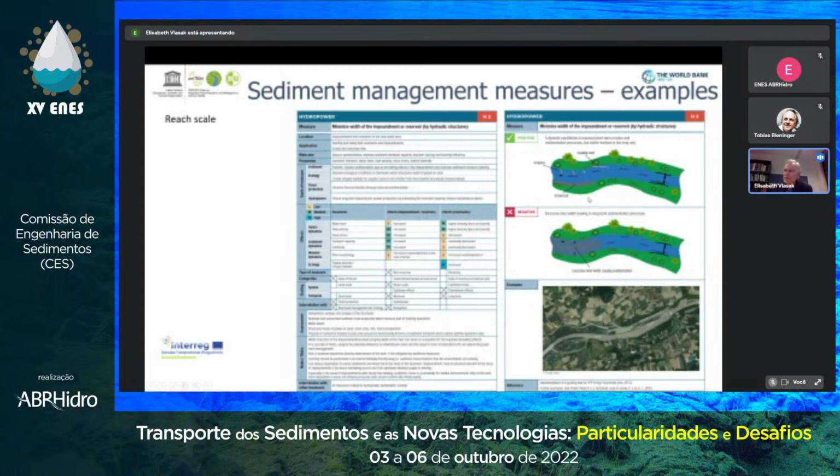Unfortunately, in our conditions in Austria, we have many reservoirs where sediment was not a part of the planning process. It has to be an integral part of the planning process, because then you can get a much better output. So the reservoir configuration is very important. Having a narrow reservoir when it comes to runoff schemes, of course, in a reservoir in the alpine environment it might be different because you need the volume. But here, just the water flow is important, not the volume. So what water flows in goes out. In this sense, we can be small and we can reduce the sedimentation by increasing the transport capacity.